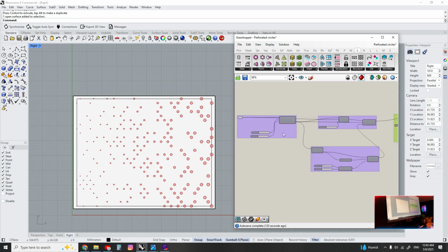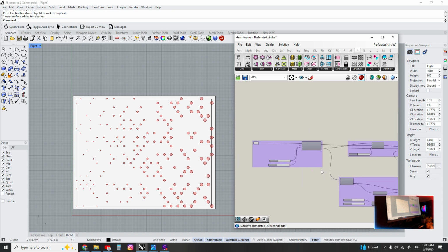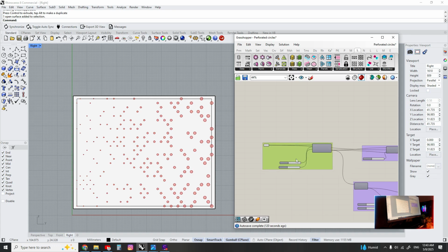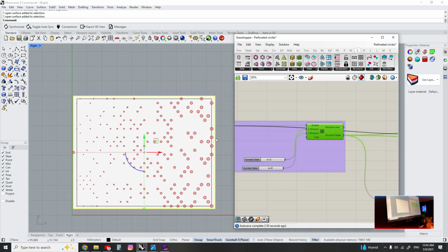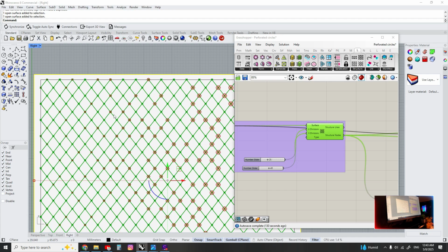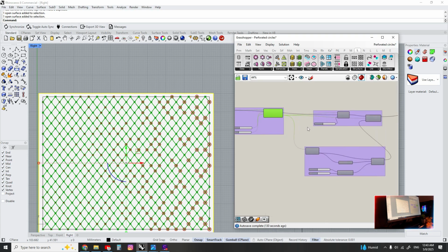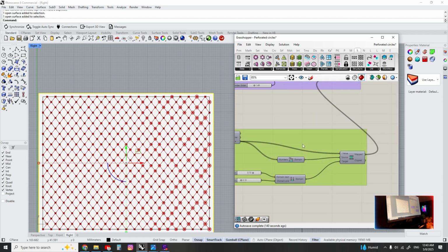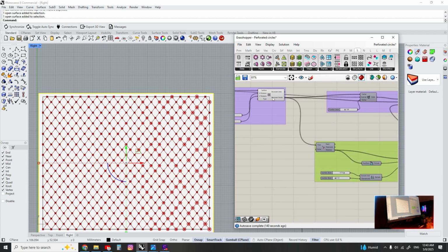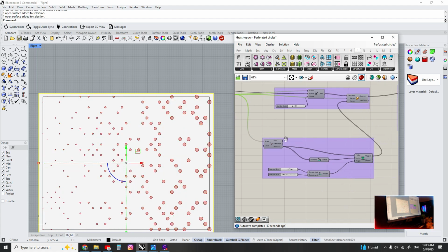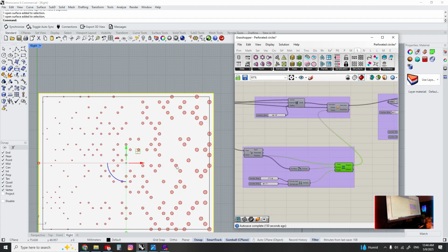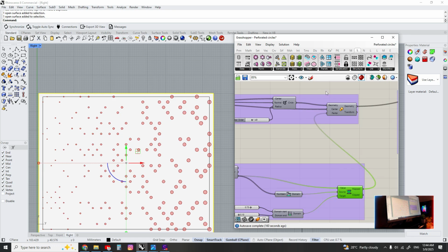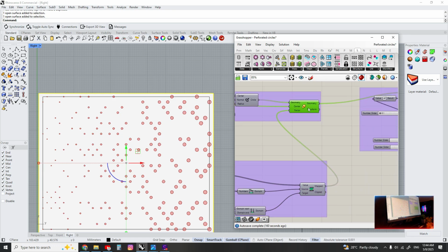Okay, our script is simply divided into 4 parts. The first part is dividing the surface and adding the nodes, so you can take it as a center of your shape. The second part is the shape, which is circle in our case. The third part is the attractor, to have the different shape of different radius for the circles, and we get this by scaling.